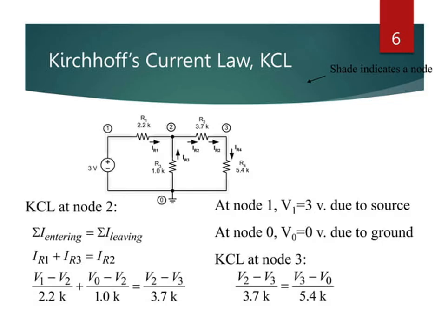Now, okay, this is an example of Kirchhoff's current law. I need to find, suppose, a branch current. Here I will not find any value, I will just show you how to write KCL. You can see this is one node. Why? Because this circuit element is an active voltage source and this is a resistor. So two elements are connected at a point, so this is a node.